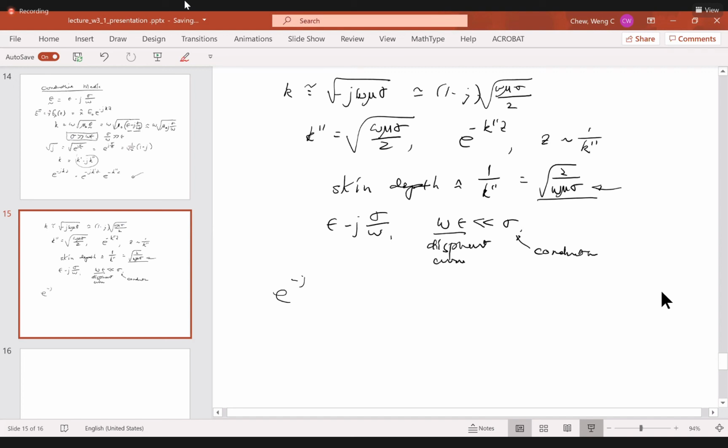So what happens is that things decay very, very rapidly. And in order to talk to your buddy, what can you do with this formula to increase the penetration depth of your electromagnetic signal? What else can you change in your radio communication device? You have to operate it at very low frequency.